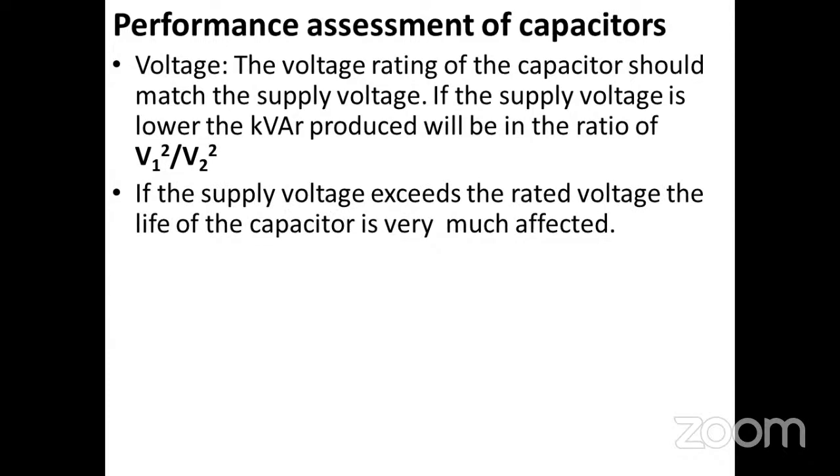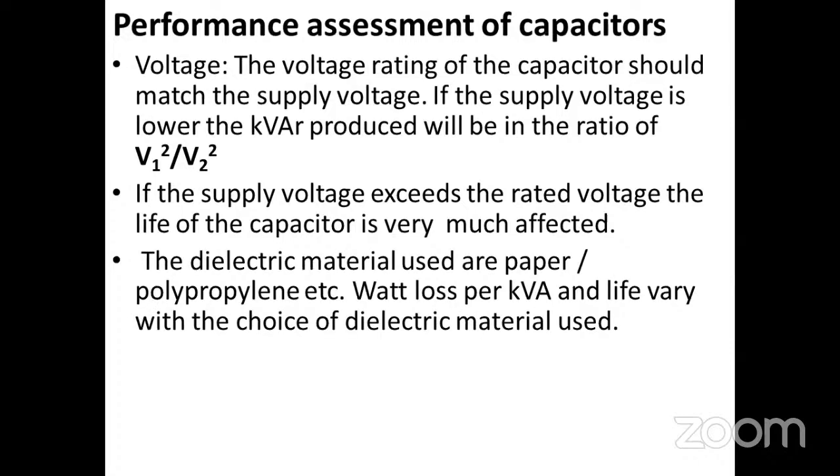If the rated voltage is higher than the supply voltage, that means the supply voltage is low, then the kVAR produced will be in proportion to V1 square by V2 square. So the effective capacitance of that particular capacitor will be very much lower if the system voltage is low.